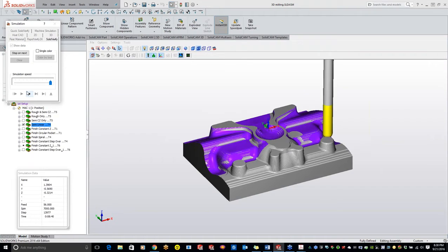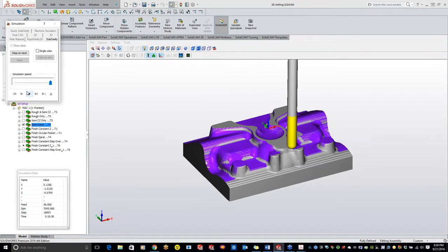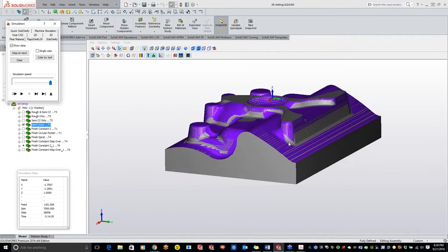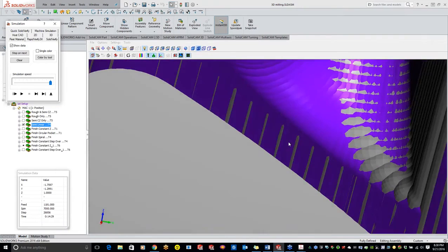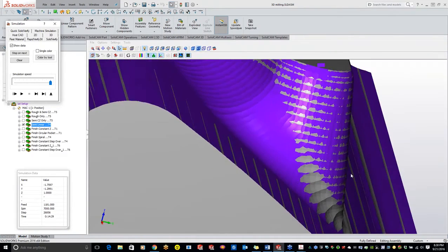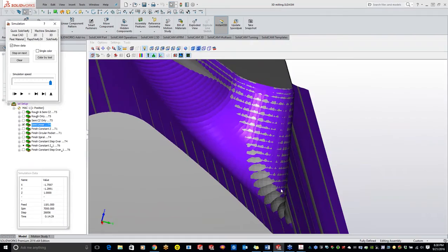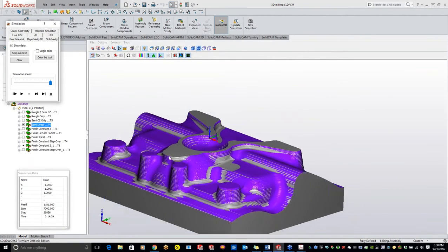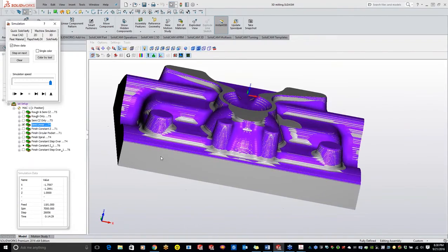Like I said, I'm not going to machine this part in full here, but I'm just trying to show you guys different examples of what the 3D milling can do for you. So we're doing a straight zigzag back and forth, just another semi-finish, knocking down some of those cusps. If I get over to this side here, you'll see that my cusp height is much smaller now, getting it much better to come back with a finish cutter in there. So we're eliminating a lot of the nubs and the bumps from the roughing operation.